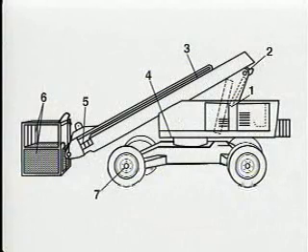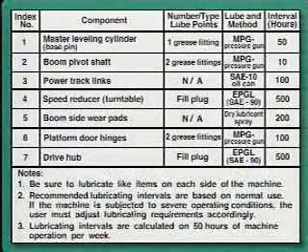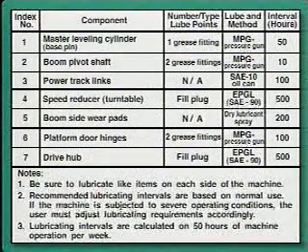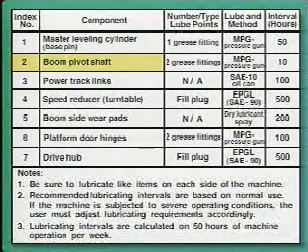Often, each lube point or equipment part that requires lubrication, as indicated on the lubrication chart, is shown and numbered on an illustration that accompanies the chart. In turn, the numbers from the illustration are listed on the lubrication chart, in this case, in the index numbers column. For instance, item number 2 from this illustration is identified as the boom pivot shaft on this simplified lubrication chart. Reading across that line on the chart, you can find the number and type of lube points.